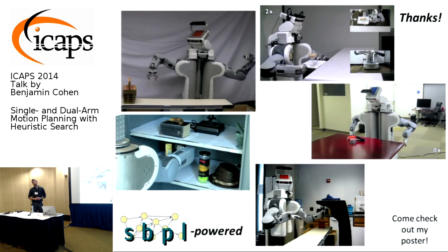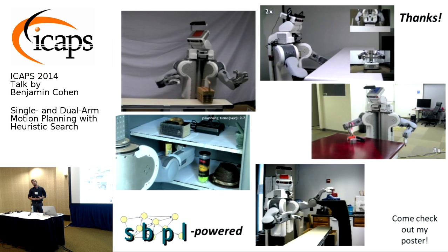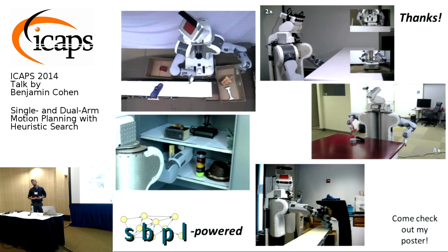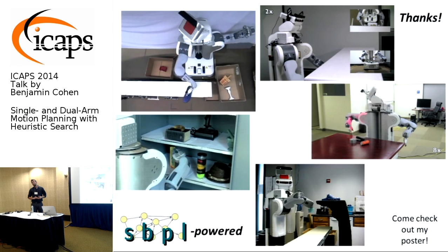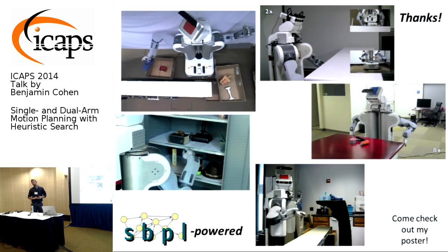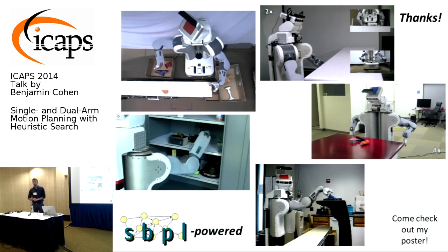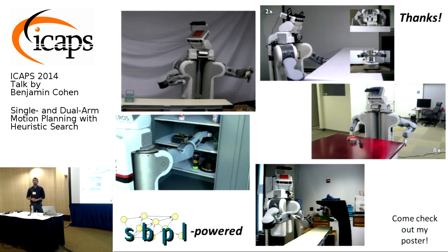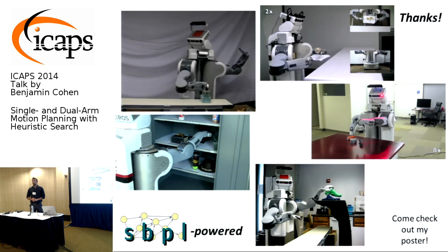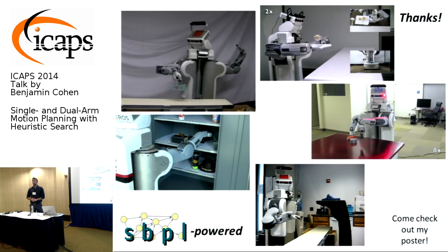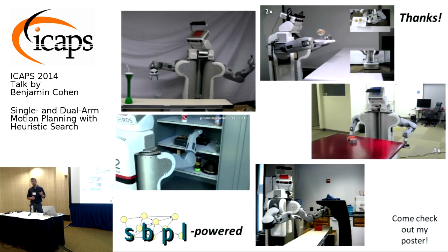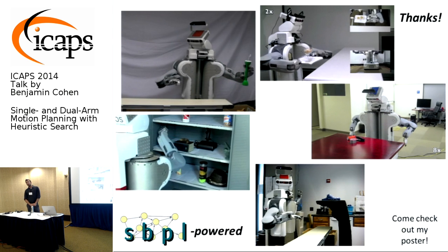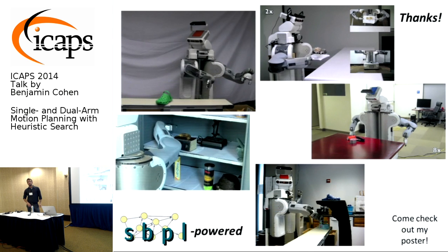It's really impressive how well these things work. I was just wondering, this A-star algorithm has been around for some time, so what do you think is the big contribution: applying the different heuristic, applying the different resolution, or making it happen in practice? We think it's the heuristic, that BFS. It takes about 100 to 150 milliseconds to run, and it's got to run, obviously, for each start-goal pair, and it gives us the biggest benefit out of all the different parts that made up the manipulation lattice graph and the other parts.